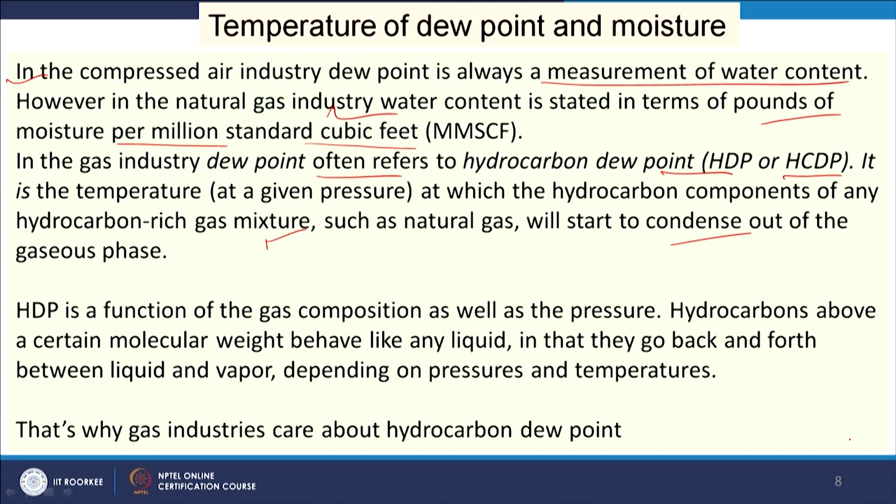So, we have seen that higher molecular weight hydrocarbon gives higher heating value, that is, LPG has higher heating value, and in this case liquid and gas phase transfer is also possible depending upon the pressure and temperature. So, the industries care about the hydrocarbon dew point. Dew point will influence how many molecules will be in the gas phase.